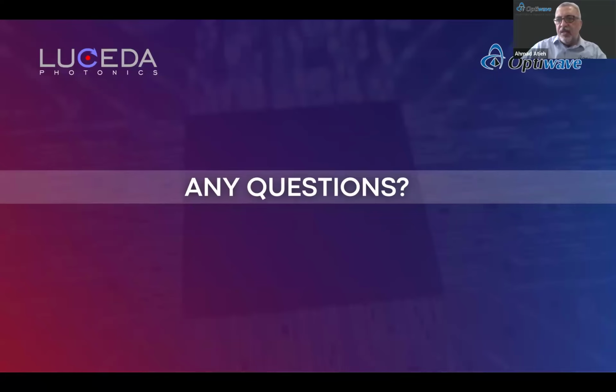Greg, the question is in chat. Is the layout to schematic transition enabled via Python script in IPKISS? So yeah, I can answer that. Yes, indeed. It's just one line of Python code you have to write, and it will export whatever circuit you draw in IPKISS to our GUI tool, which is Canvas. Does that answer your question?